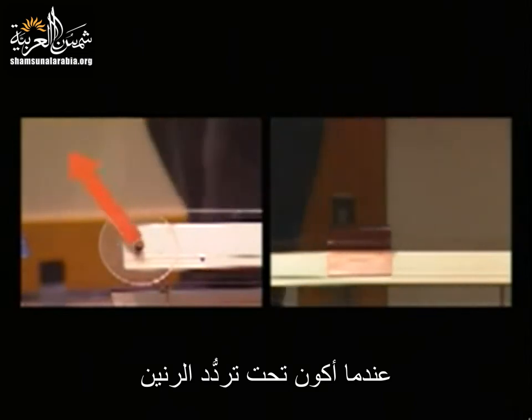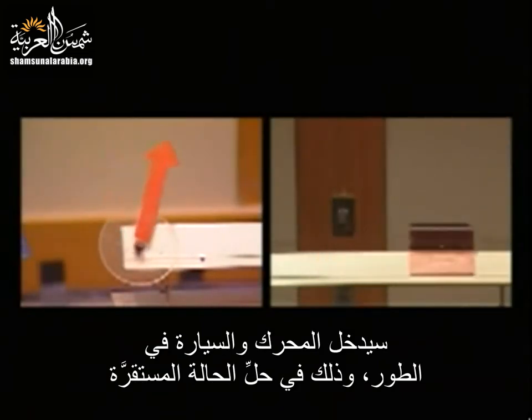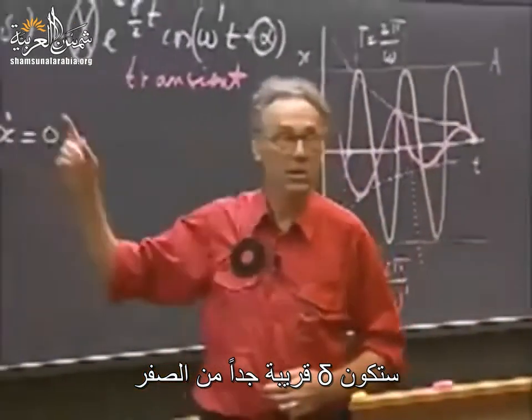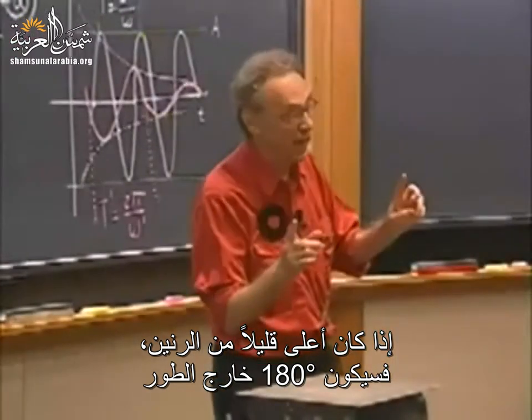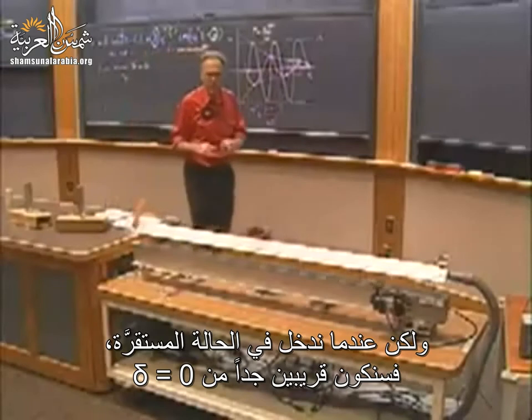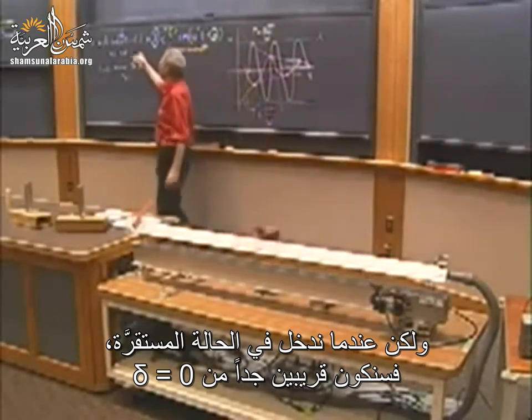It's a very high Q system. Since I am just below resonance, the driver and the car will be in phase when I'm below resonance in steady state solution. So this delta will be very close to zero, below resonance. Above resonance, 180 degrees out of phase, but I'm just below resonance. So when we go into steady state, we also will see that we are very close to a delta of zero.